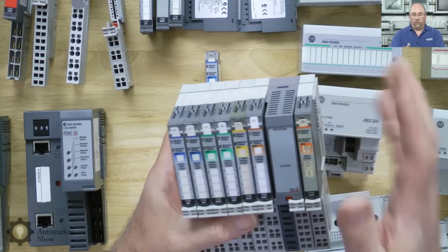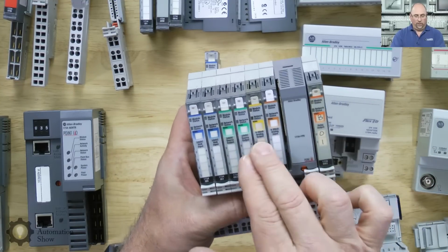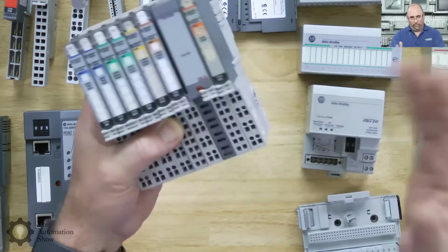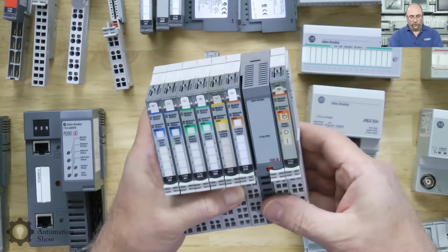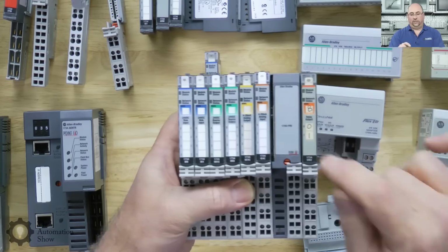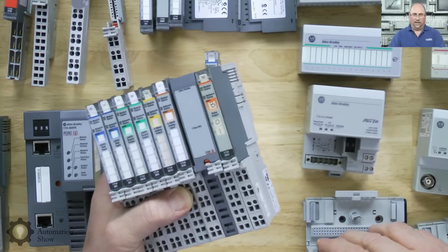So that is used either to isolate, sometimes you want to isolate your digital I/O from your analog, so you put one in there. Or you definitely need to isolate the power bus from DC to AC because of different voltages, right? So in any case, that's something different with the Point I/O that you didn't need with the Flex-IO.